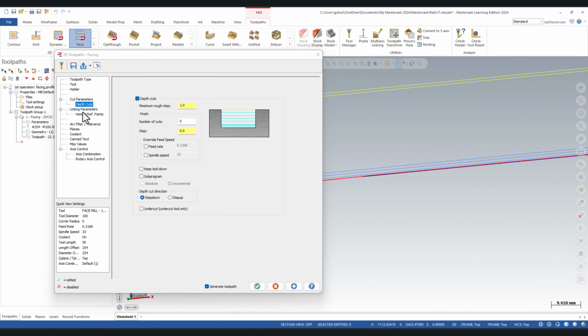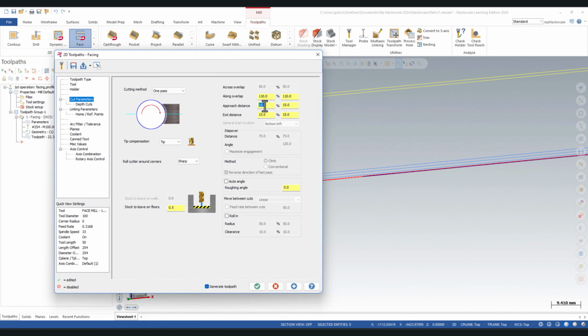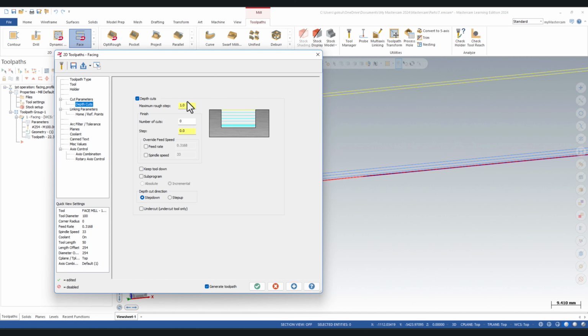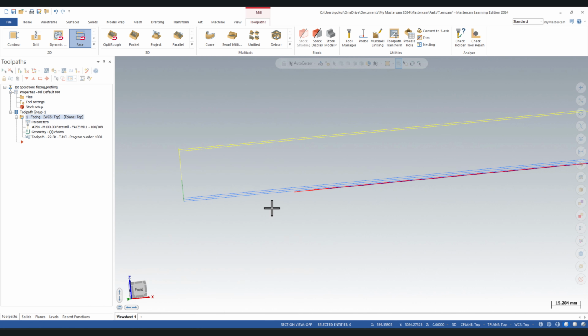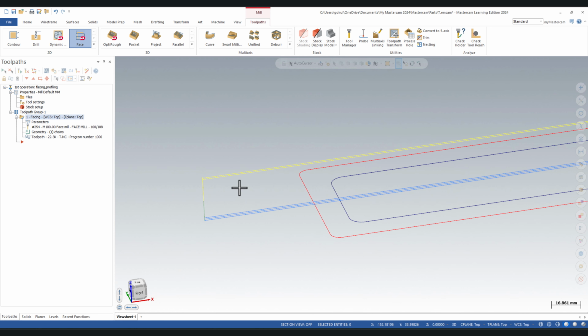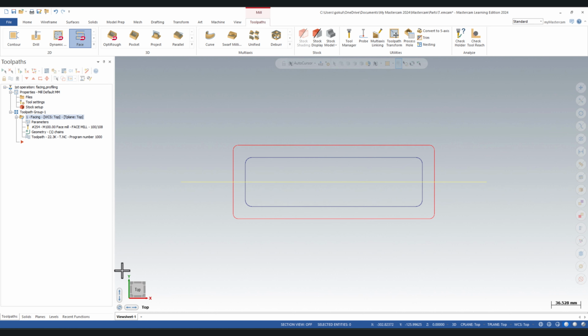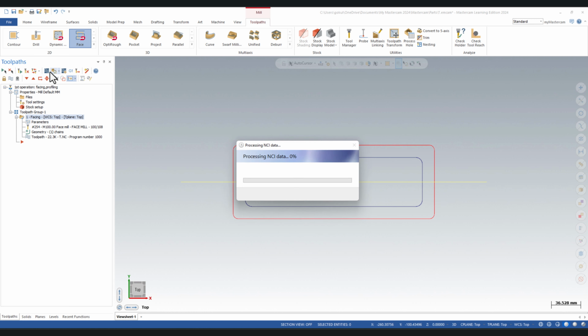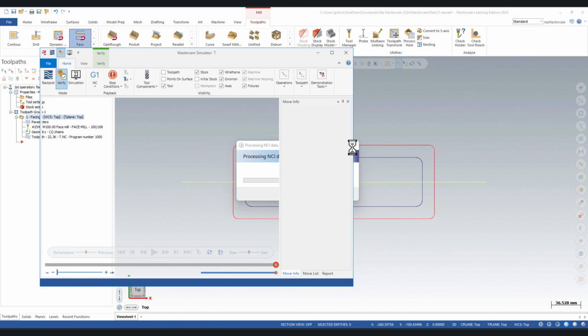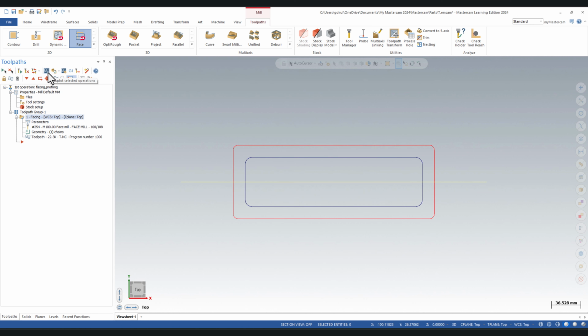Okay, so again go for parameters. I need it as it is, and I am just leaving this as 1 mm. So see here, the toolpath has been generated. Now to cross verify that, I am just clicking top plane. You can do 2 types of verification, because it does not have a stock, the verify is not working. So I am just going with the back plot option.